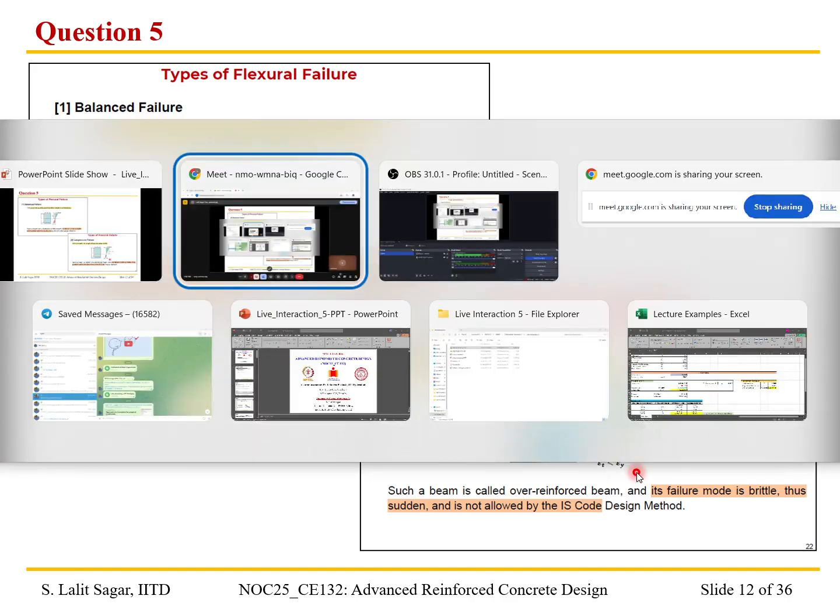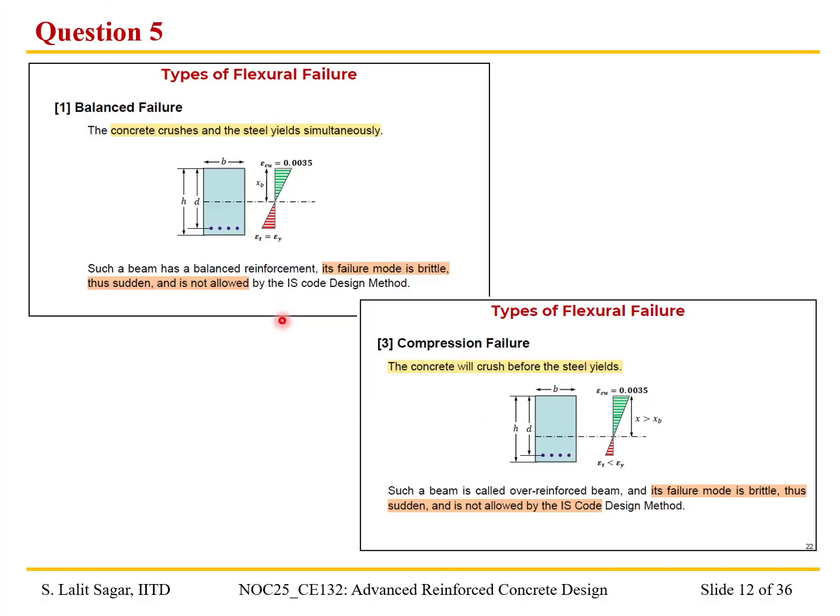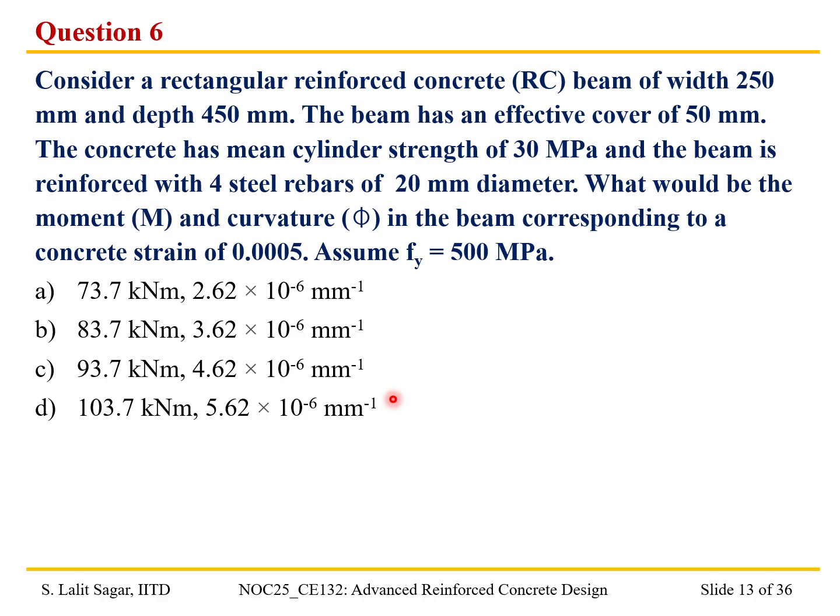And again, as I explained previously, for the same reason that the mode of failure is brittle and sudden, the balanced failure is not permitted, and similarly, the compression failure is also not permitted because of the inadequate deformations in the beam. Moving forward, we'll proceed to the next question.